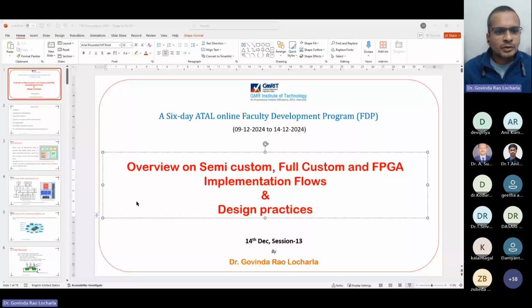And here, the application processor handles all our user apps. This Bluetooth block handles the Bluetooth wireless data, this Wi-Fi block handles the Wi-Fi wireless data, and similarly the GPS block. Each block is composed of a CPU, typically in most cases an ARM processor, and RAM, ROM, and a couple of peripherals and a bus connected across them.